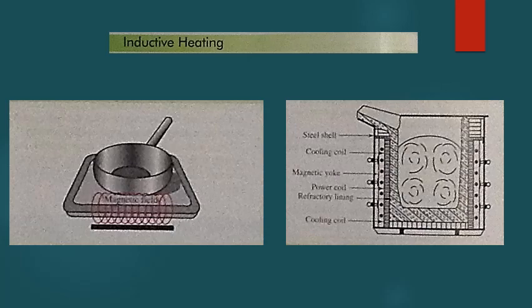In this stove top, a cooking unit is designed with a coil located under the ceramic top. When a metallic or some other induction efficient cooking pot is placed on the cooking top, a magnetic field is induced by the coil hidden beneath the counter surface. The coil does not produce heat in the same manner as a conventional electric cooktop. The conventional electric cooktop uses resistance wire inside coils to produce heat.